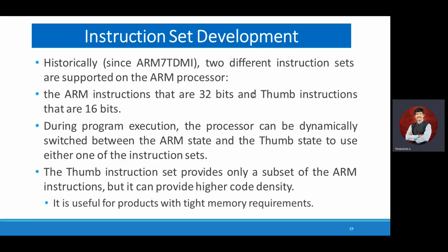Say my data is only 8-bit; if my microprocessor 8086 is a 16-bit processor, even though the data is 8-bit, I have to use the 16-bit register itself. It is consuming more memory and more time. The remaining 8 bits we are adding, we are supposed to pad them with zeros. We have to fill them with zeros itself.